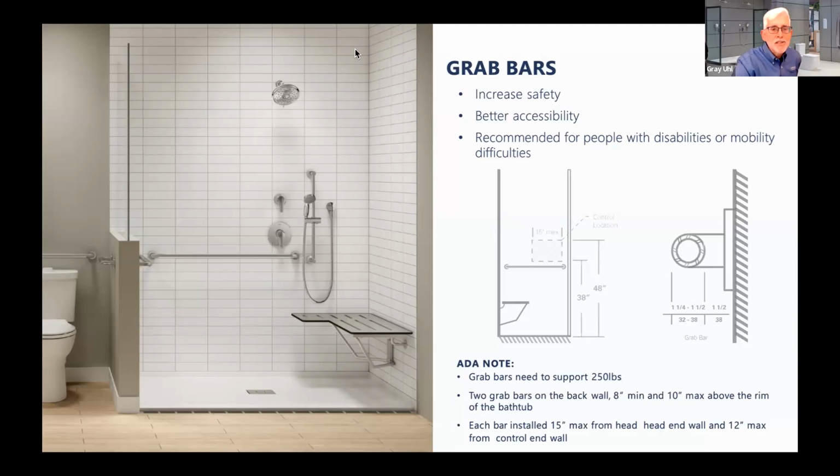The reason I tell you this is there are very strict requirements for where grab bars have to be located and what shape the grab bars are. Very strict requirements in ADA. If it's a public ADA, typically a residential shower system is not ADA, and there are not these requirements. And there's a bunch of great grab bars on the marketplace that don't meet ADA, but certainly are wonderful features to have.